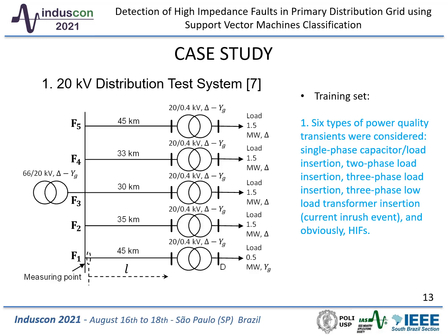MATLAB. Taking into consideration that in MV distribution systems, loads are generally fed by a step-down transformer, in which the MV side is usually wired without neutral lines, the residual current measured at the MV terminals, the measuring point, is almost unaffected by the loads present at the LV sides. Non-zero values of residual currents can be attributed to load transients, earth faults, or normal transient phenomena along the feeder.